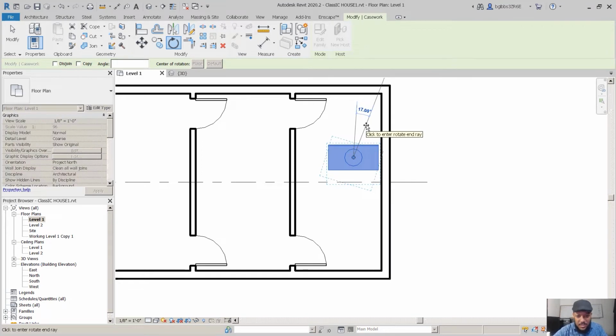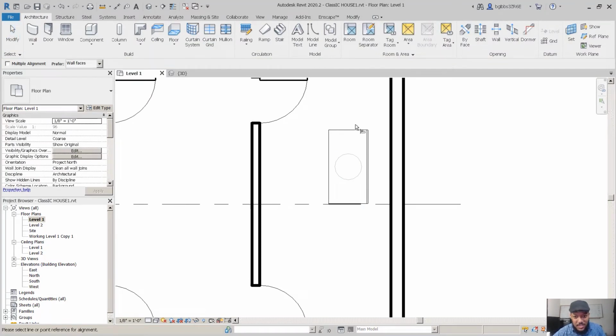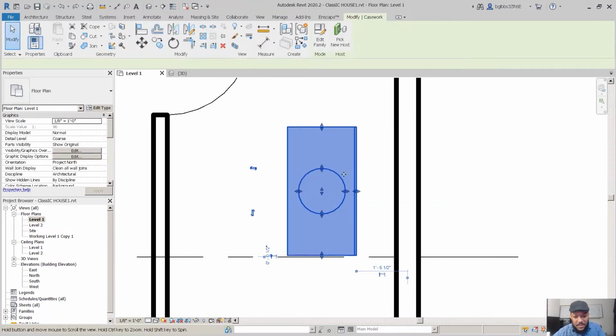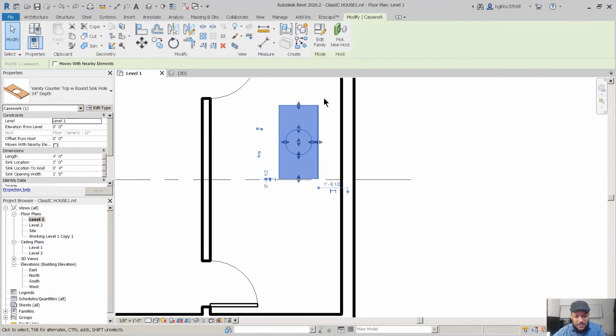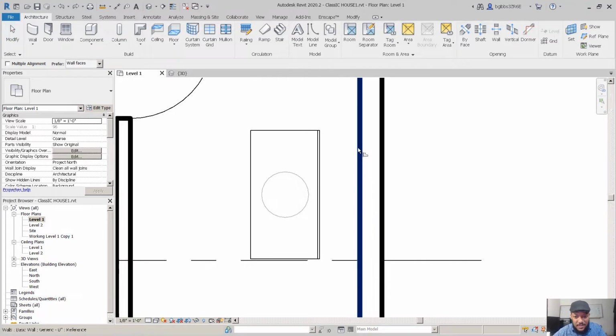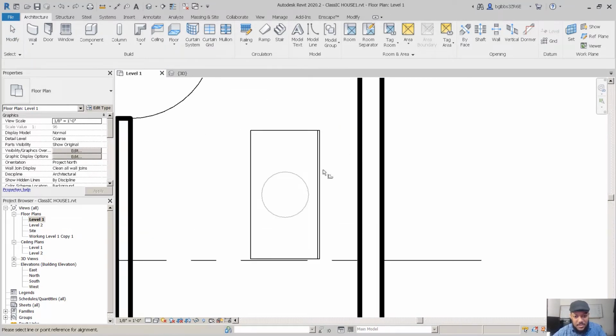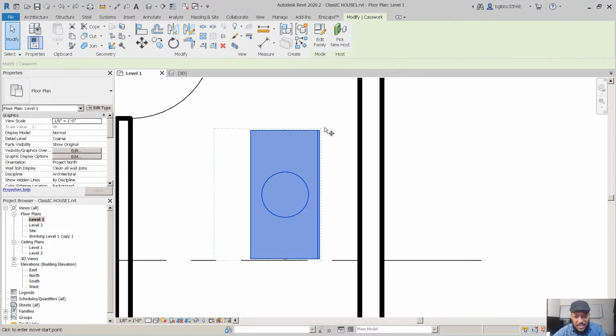And we're going to rotate this by 90. I just clicked R, but you could also click on this button. And I'm going to start using Align a lot more. Just press AL. Align is also in the Modify tool. And we're going to undo that. Sometimes the family parts move separately. When I pressed Align here, it only aligned part of the model. That's how the family's set up. So sometimes you can use it, sometimes you can't.